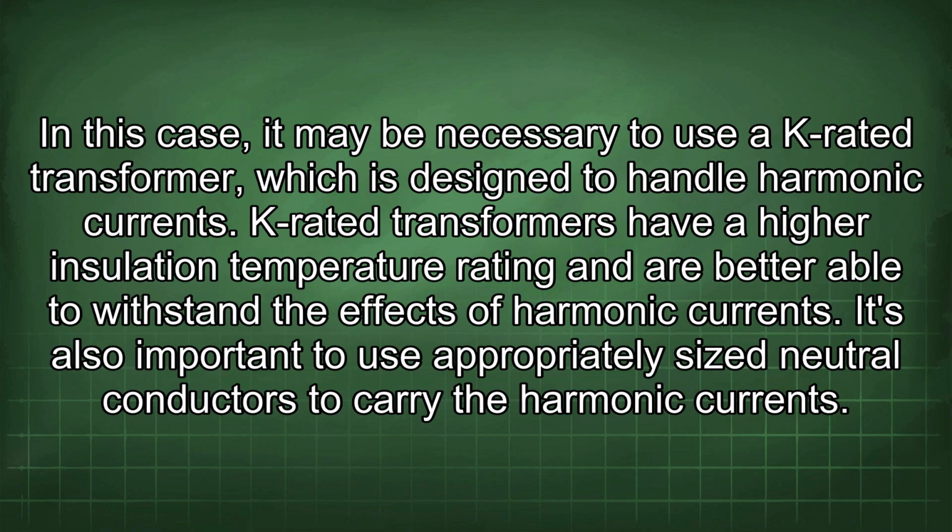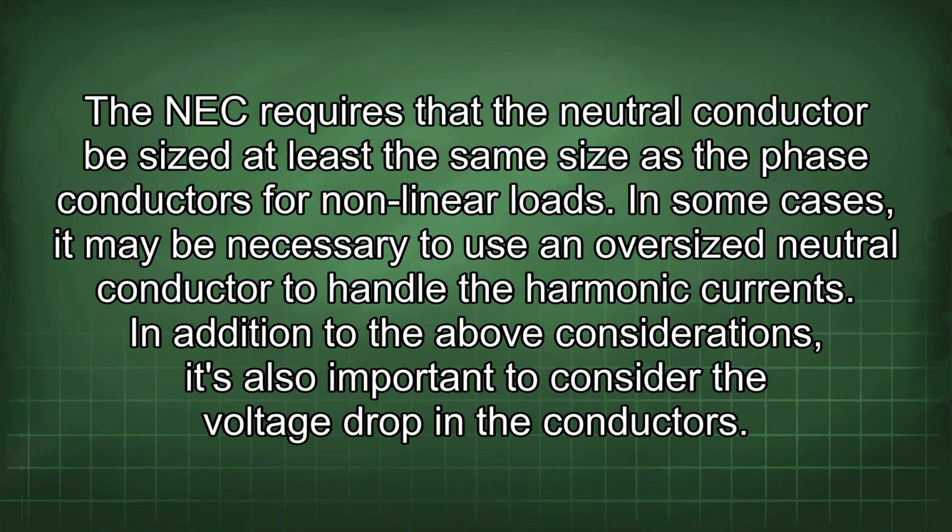It's also important to use appropriately sized neutral conductors to carry the harmonic currents. The NEC requires that the neutral conductor be sized at least the same size as the phase conductors for nonlinear loads. In some cases, it may be necessary to use an oversized neutral conductor to handle the harmonic currents.